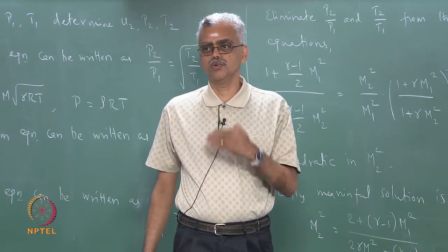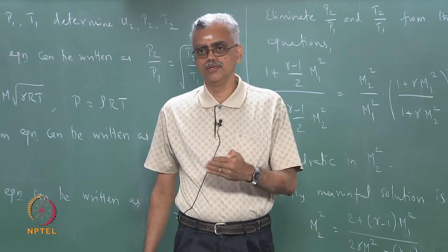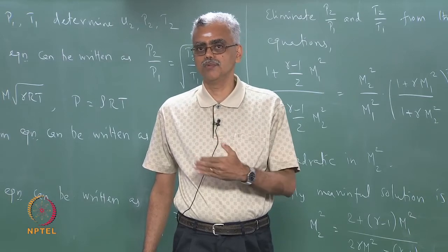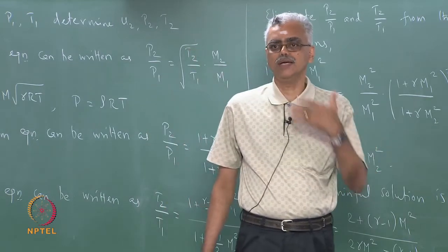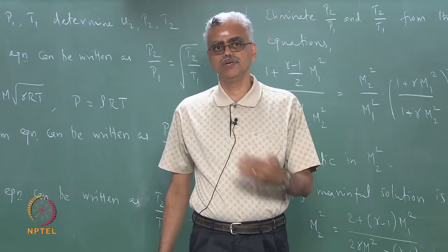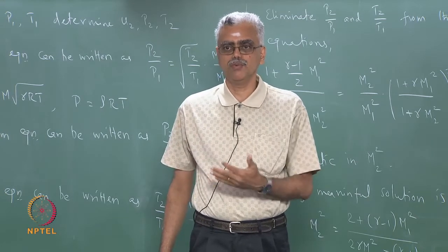That is permitted because a Prandtl-Meyer wave is an isentropic wave. There is no change in entropy across the wave. It represents an infinitesimal compression. That is permitted. What this talks about is a finite compression or finite expansion. Finite compression is permitted, but finite expansion is not permitted. So we cannot have these types of expansion waves.